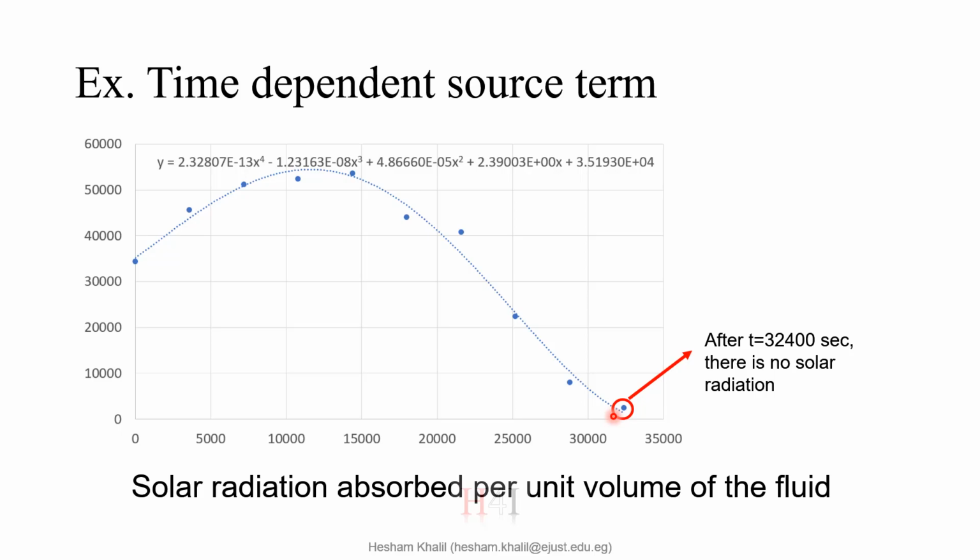The description of the case, or what? So you said it becomes 0. You said the solar radiation becomes 0, right? Yes, solar radiation equals 0 after this time. So I need an if condition: if the time is before 32,000, it will use this expression, but after 32,000, the expression must be 0. Yes, I need to define this in the expression window.